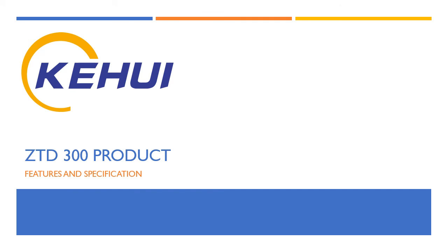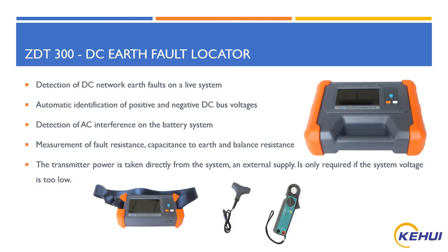Coming to the product features and specifications, you have a transmitter unit, a receiver unit, and a sensor. You get two different sensors with this particular supply. This equipment helps you to identify the DC faults in the live or online system. It also gives you clear automatic identification of positive or negative bus voltage drops. It gives the information if there is any AC interference in the battery system. It measures your fault resistance, the fault capacitance, and also gives you the information of the balancing resistance.